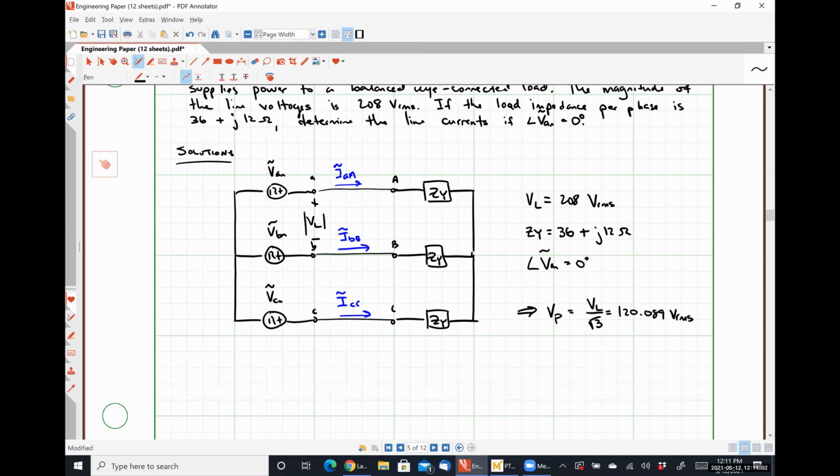So you get a 240 volt and you split it in half by literally just putting a center tap on the transformer, and then you get access to from ground up 120 and then the other way is negative 120. And if you connect things from both of the hot wires, it looks like 240, which is how your dryers and all that kind of stuff get powered.